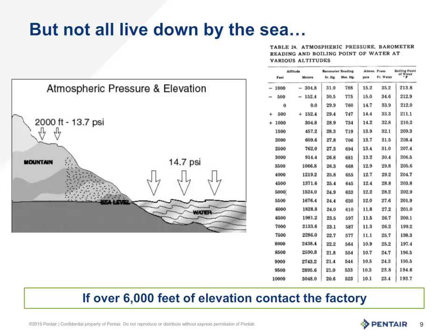And yes, this means that for every 1 psi lost due to this elevation, you also lose 2.31 feet of suction lift. An additional word of caution, if you are really cutting your calculations so close, even barometric pressure can change with storm fronts moving in and out. So always give yourself some room when designing a system. No one wants a waterfall that only works when the barometric pressure cooperates.